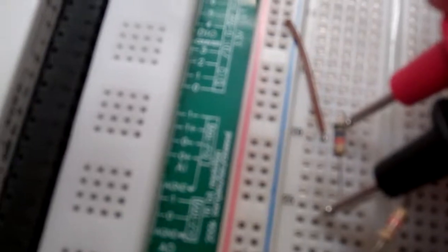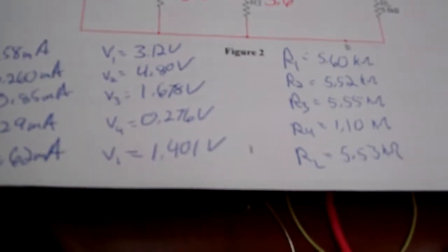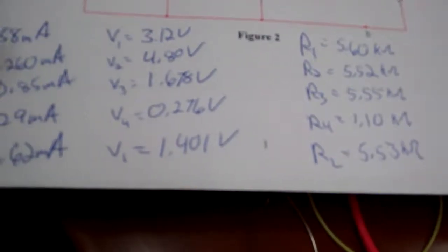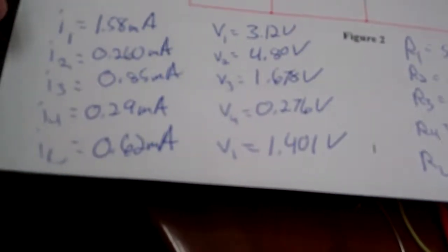across each of the elements, again I can't do this one-handed, but you put the probes across the 2 ends of each of the elements, and then that'll give you the current and the voltage when you switch the multimeter settings. And what you'll get is a series of values. You'll see here you have resistance values for each of the resistors, and then the voltage and the current.